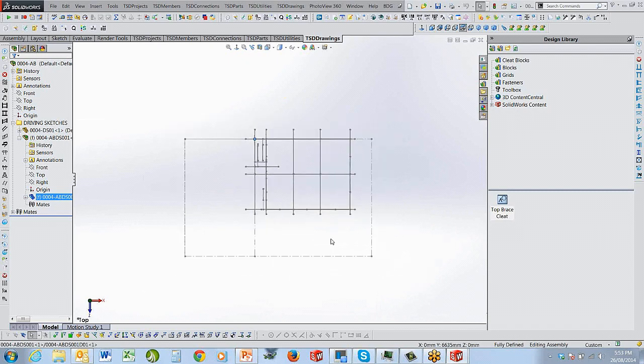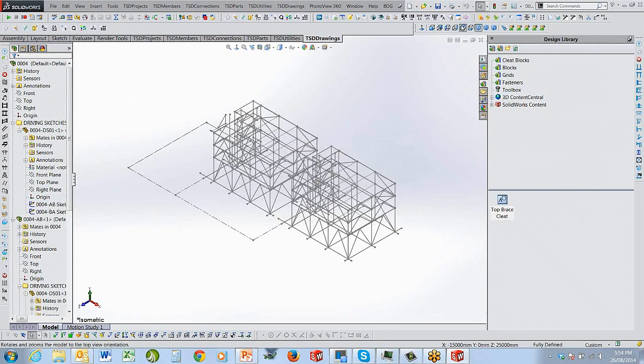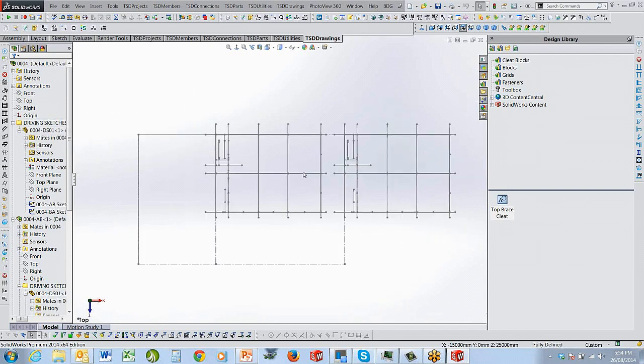So what that means is if I was to go and drop area AC, not AB, over the top of this one, you will notice something very interesting, because you actually have to position the driving sketch at its origin to get them in the right locations at the top level assembly, and that's basically what we've done. So in an area, you want to make it so that each one of these areas at this level, if you're going to create a GA at the area level, you do not want it moving, but at this level you have to have it moving. And to do that is to just simply overlay the driving sketches and mate them together.